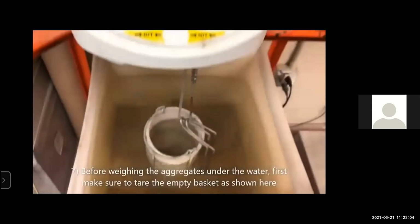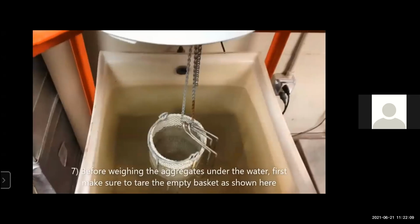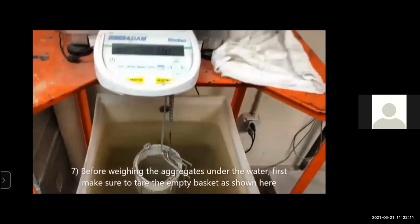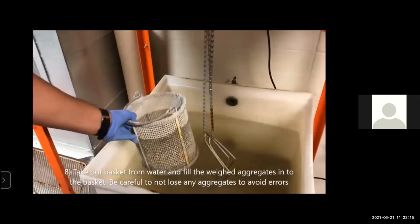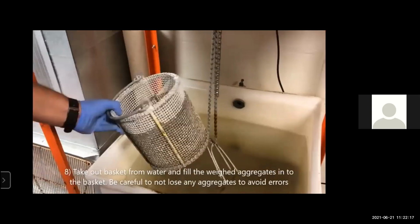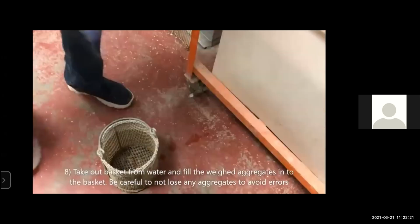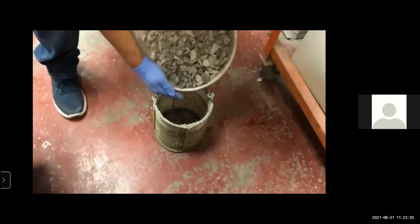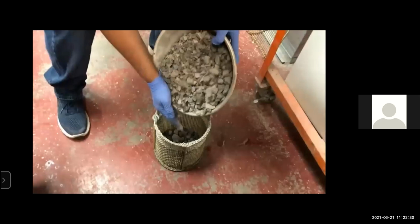So before weighing the aggregate under the water, first make sure to clear the empty basket as shown here. So basically we wet our empty basket from this water container. Take the basket out of the water and fill the wetted aggregate into the basket. Be careful not to lose any aggregate to avoid error. So basically here we put all the aggregates completely in this basket.